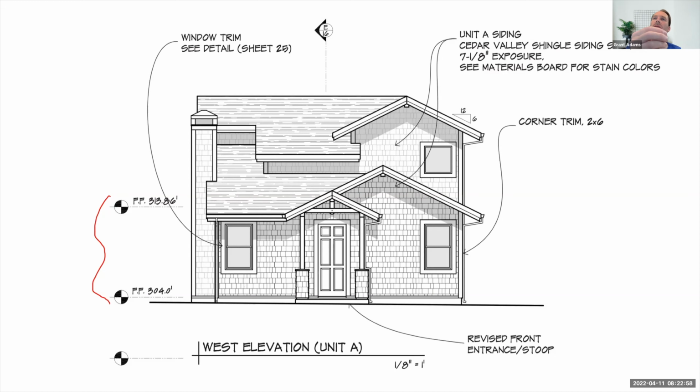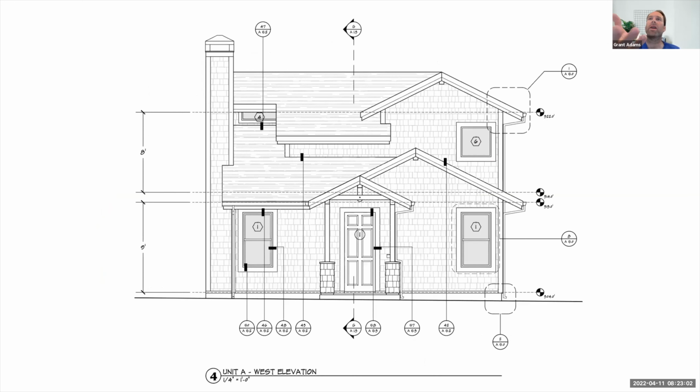After the approval of this, when we went to actually construct the building, there's yet a third elevation. This elevation became the construction drawing elevation. And you see that there's lots more detail references, very specific spot elevations. There's window callouts, door callouts. So there's a lot of real technical information that's included on this sheet that isn't included in any of the rest of the sheets. There are still line weights, it's still important, but they're de-emphasized a bit.